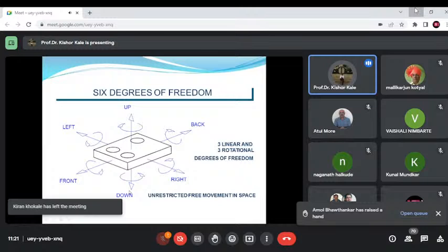Now with respect to this, it is very difficult to measure how much the height is and all this. So we have to select the primary datum in such a way that it has a functional relationship, it should be accessible, and then it ensures the repeatability. Okay. So here you see the primary datum is shown. First datum established by 3 points. Minimum contact with simulated datum A.